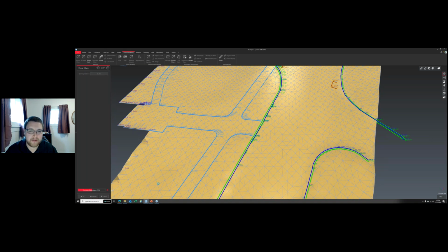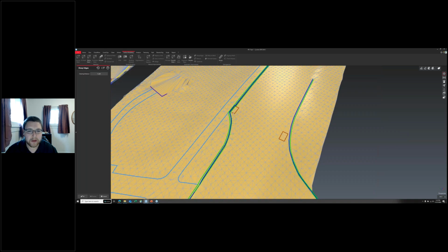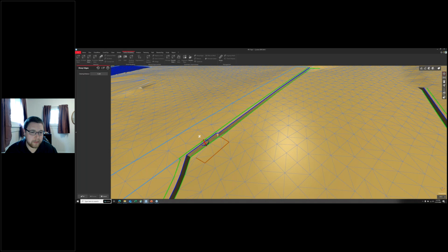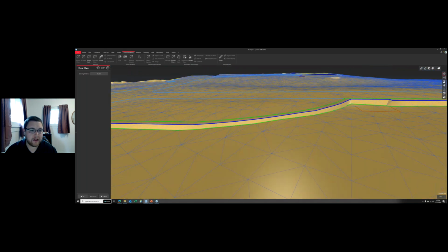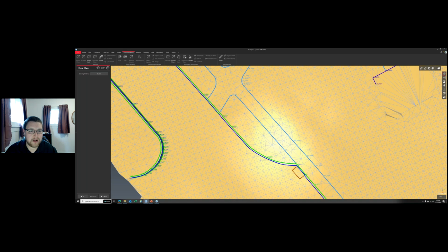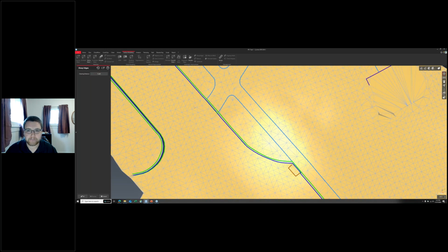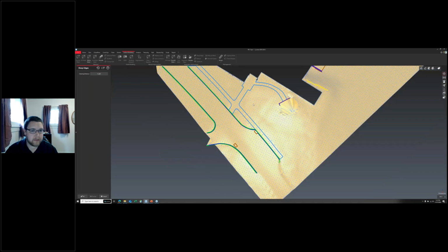I'm going to run preview, and you can see that it does some cleaning up here. My curb already shows much better. I actually have my curb in there. That worked really well, and these triangles along either side have cleaned up. Sometimes for the sidewalks I may want a 10-foot cleaning distance instead of the 5-foot or 3-foot, so I may add things in at different intervals. I'm just going to hit OK there.